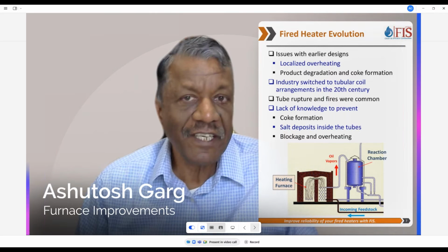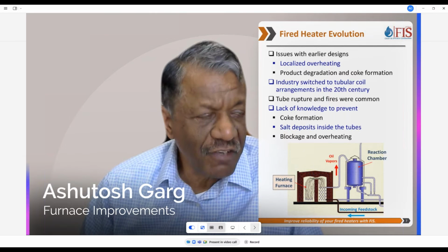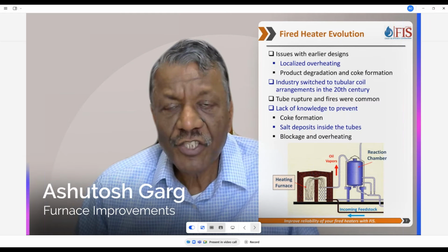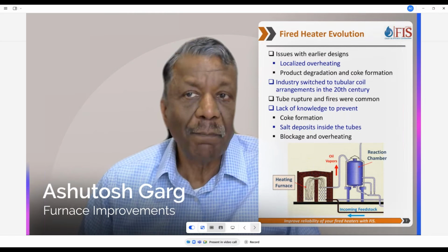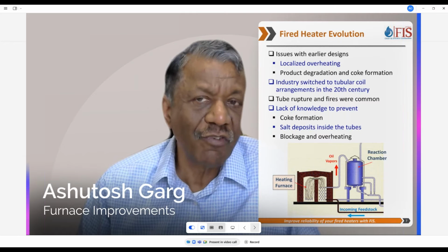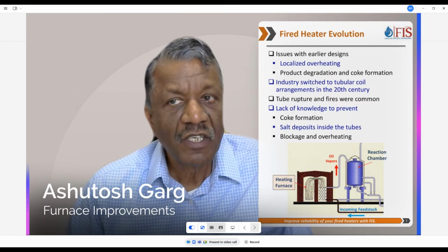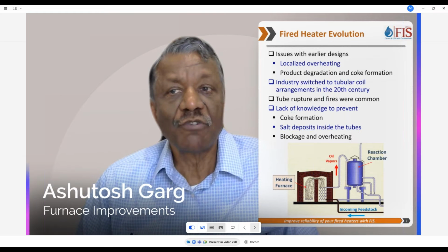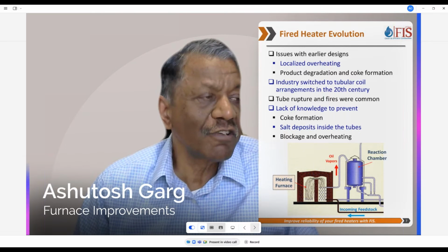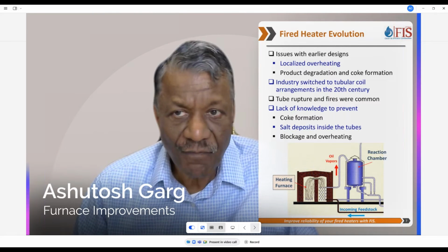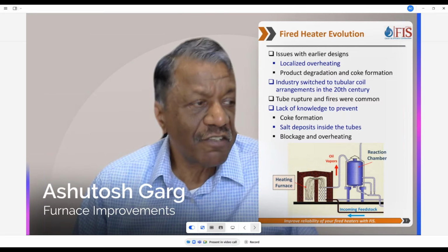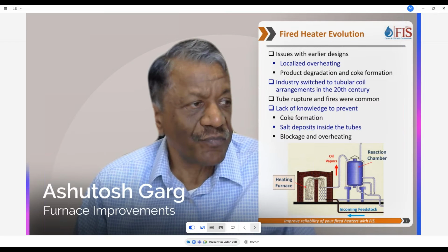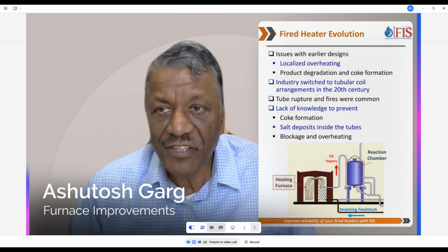That was the next stage in the development of fire heaters: instead of a shell, we used pipes. Using pipe was a big step forward because it allowed a very great surface to volume ratio as compared to the shell. The fluid was also flowing at high velocities. These pipe stills were basically constructed like a pipe bank. You can see in the sketch what is there in the presentation here.